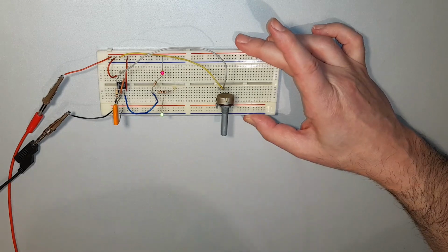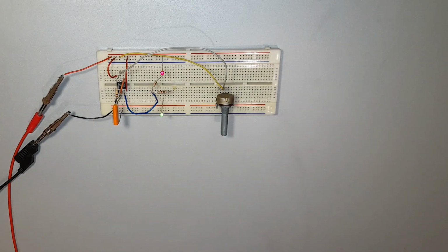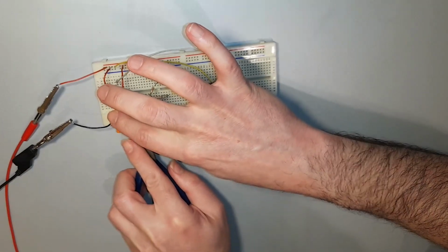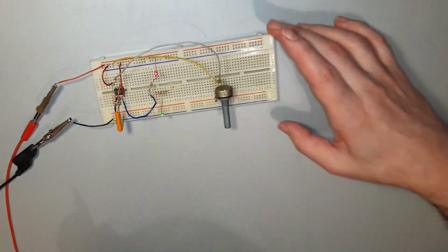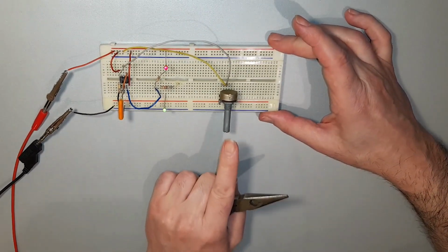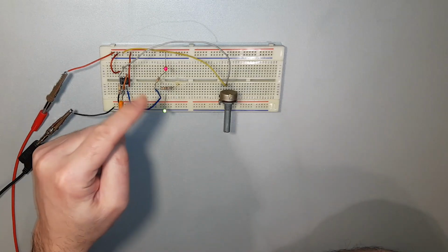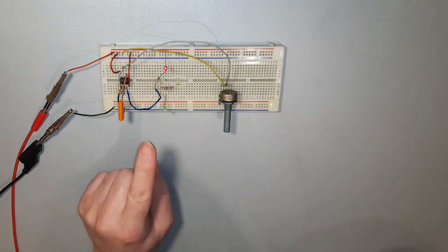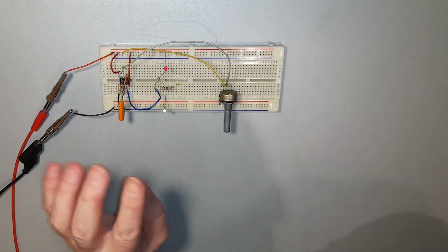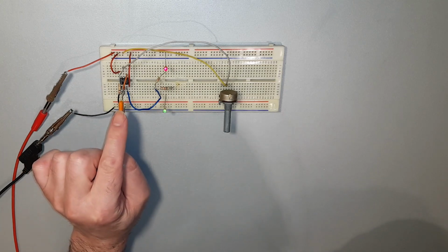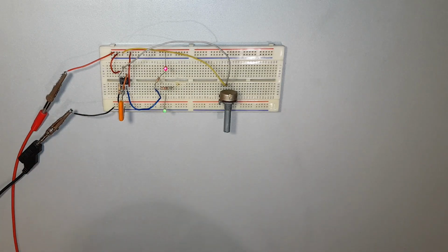You can see it's blinking away like crazy. I need to push this in nice and steadily, like that. So I've not adjusted R1. We now have this quite a high frequency blink. So what we're going to do now is see the mark to space ratio with this lower value capacitor. We're going to look at the waveform on an oscilloscope.